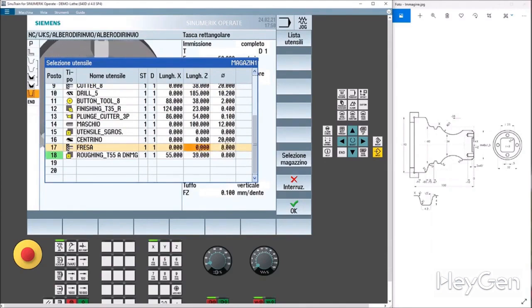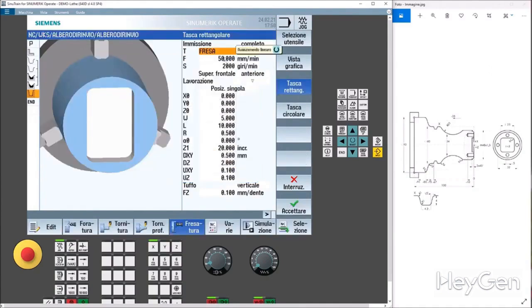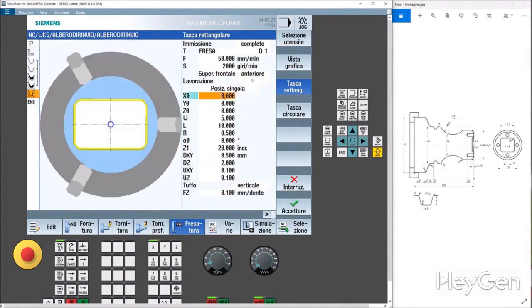Let's take an 8 cutter. That's perfect because this is a diameter. So, okay. We'll work at 2000 RPM, 50 millimeters per minute. Let's take a moment to rough it out. For now, we'll proceed by roughing it out thoroughly and executing it in one continuous effort, just as we typically do in our usual approach.